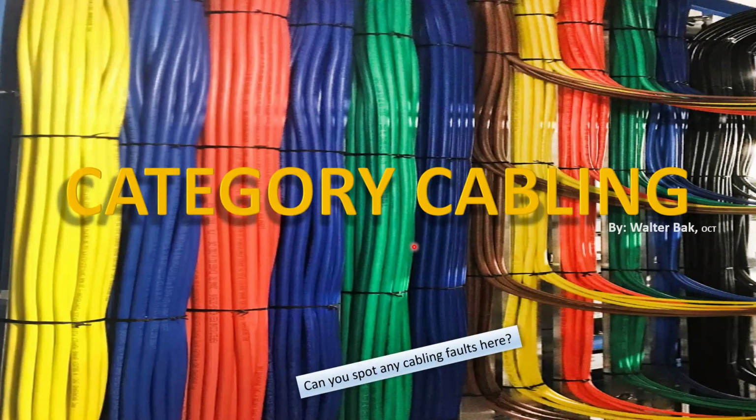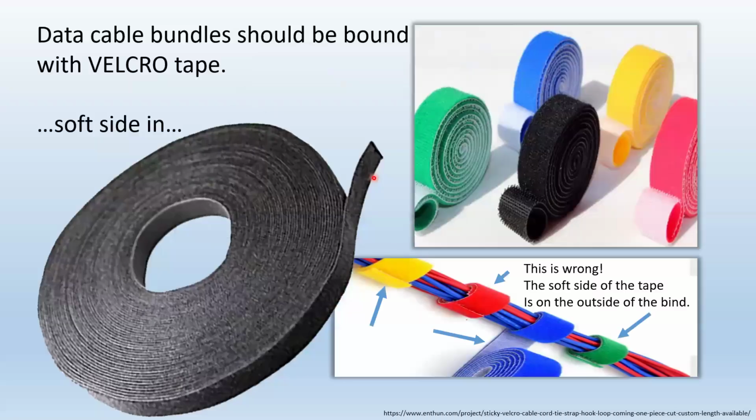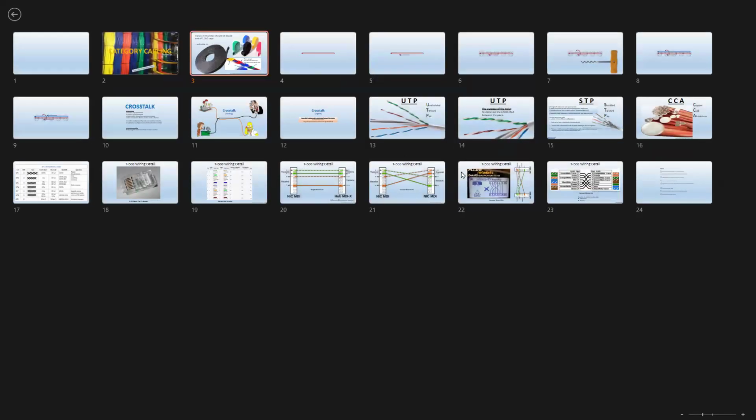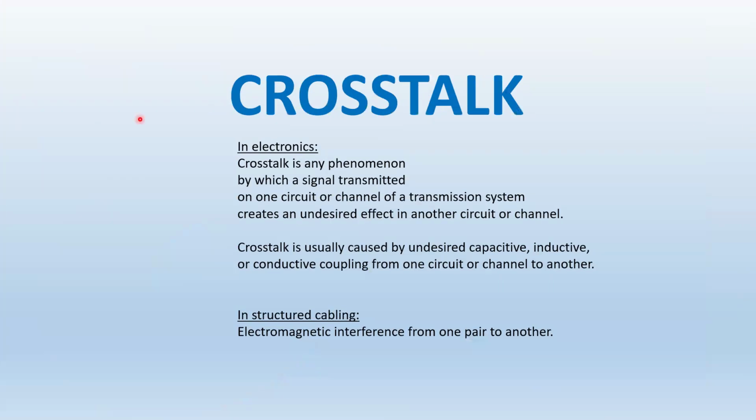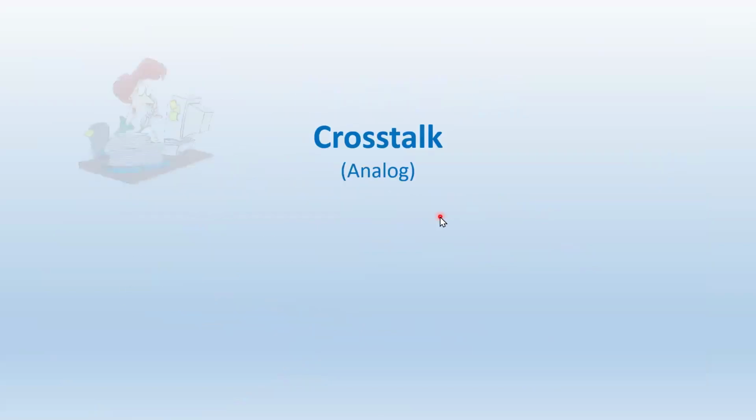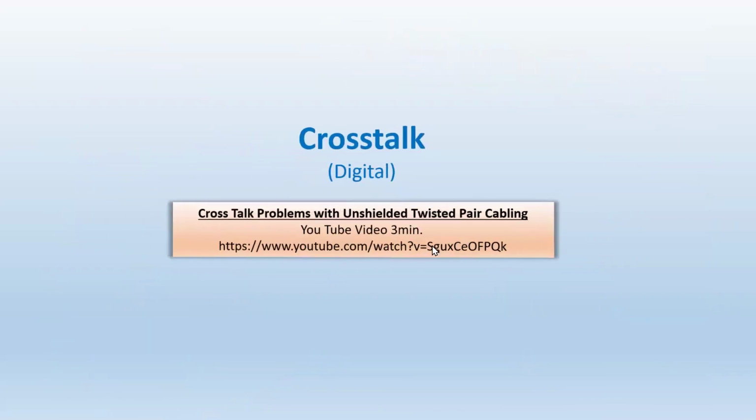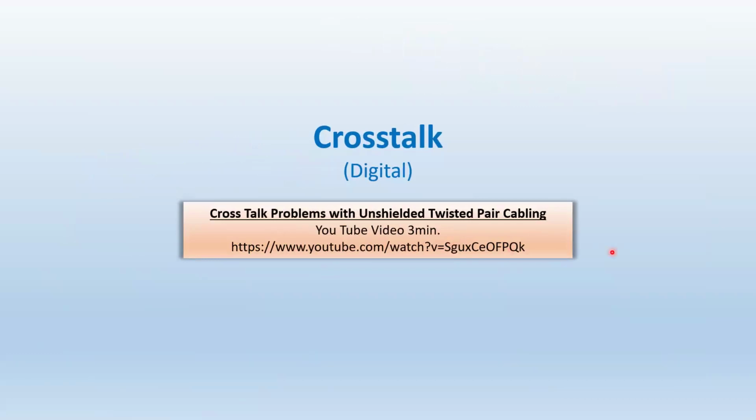Because on one hand, I'm showing you that there's just two cables close to each other and the signal dies out, and here is a bunch of cables close to each other. How come the signal doesn't die out? Well, as I said, that is an extreme. It just shows that sometimes we need to use cables that are shielded.